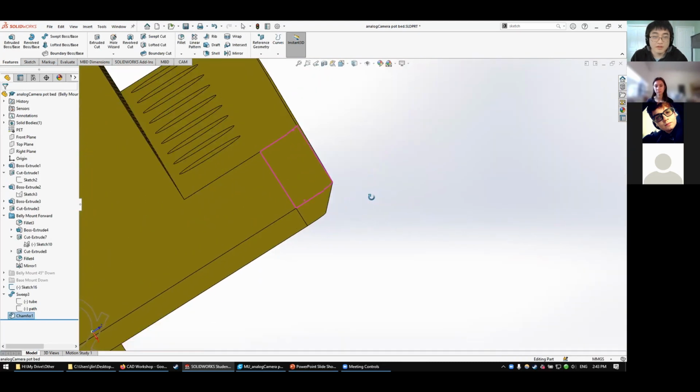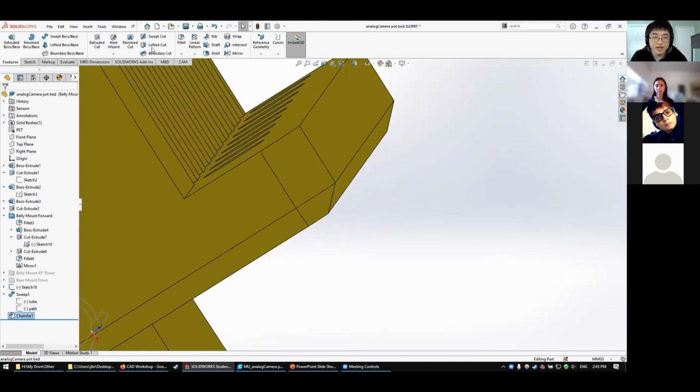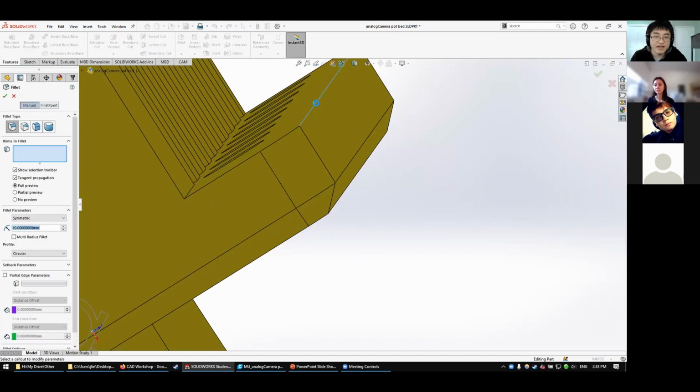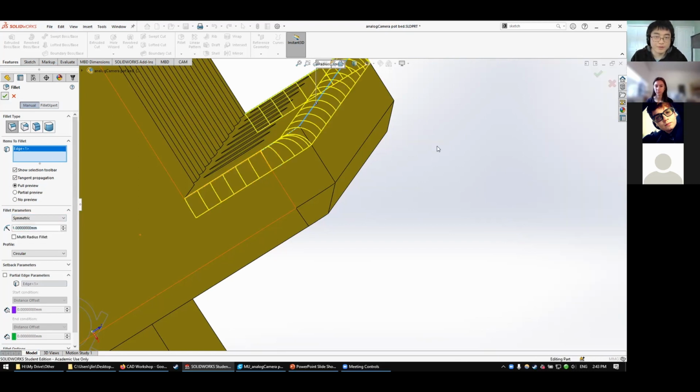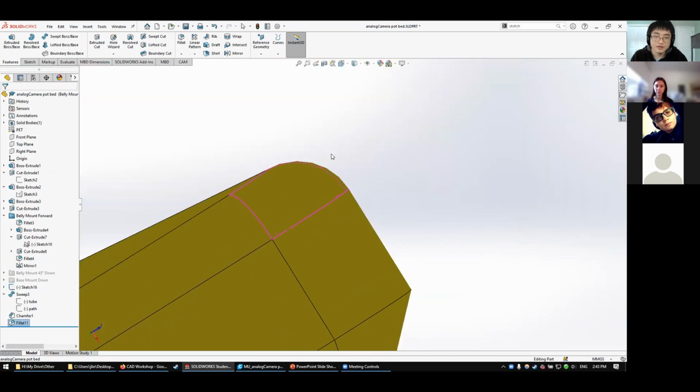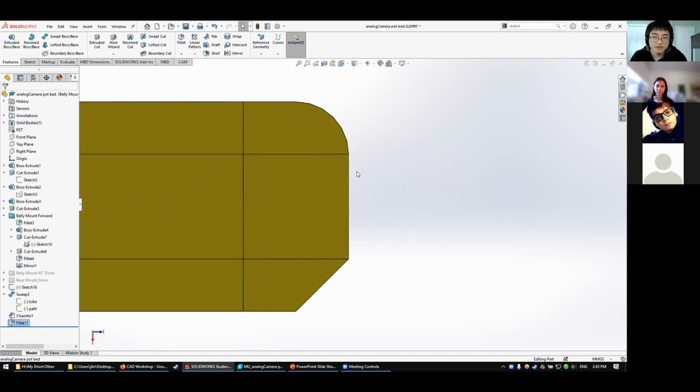Chamfer and fillet both function very similarly, as in the buttons used to operate them are very similar. You select an edge or a number of edges, select the depth, and then it will cut it for you. Fillet, rounded; chamfer, straight cut. Nice things to use, they make your design a little bit cheaper and also easier to hold.